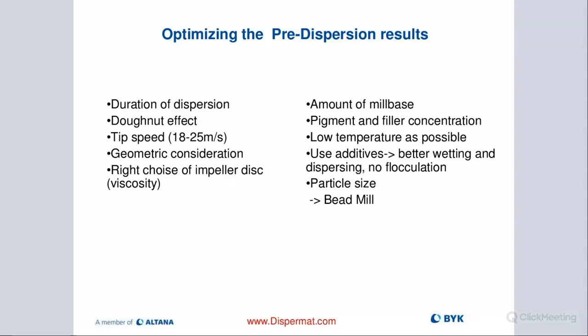Of course, when we are milling, we're going to put in a lot more energy, so it becomes very critical that we have that type of jacketed vessel. And ideally, we also want to be able to cool our mill head. Basket mills or even horizontal mills or our IPS system also have cooling jackets that allow us to really control the temperature and keep it in a manageable range, so as not to overheat our mill base. So that's very, very important.